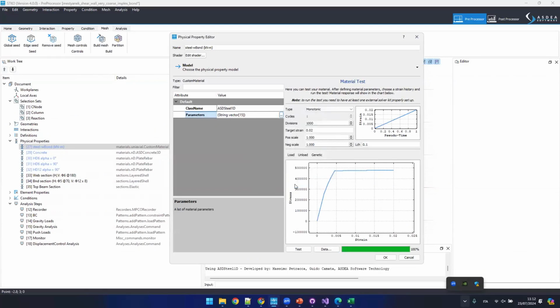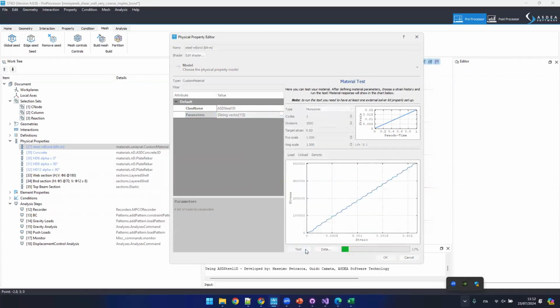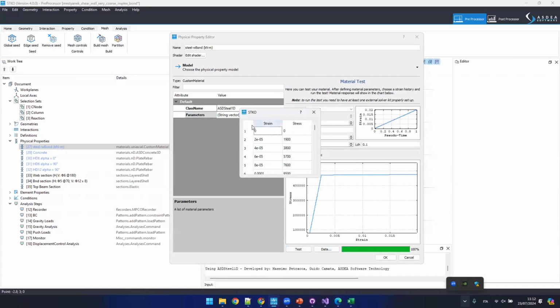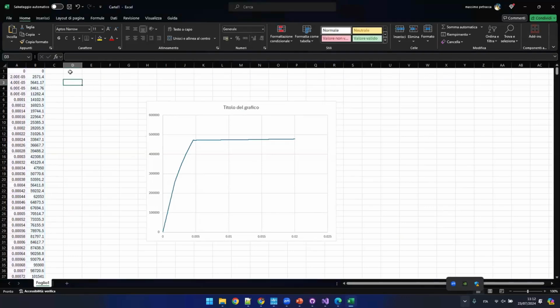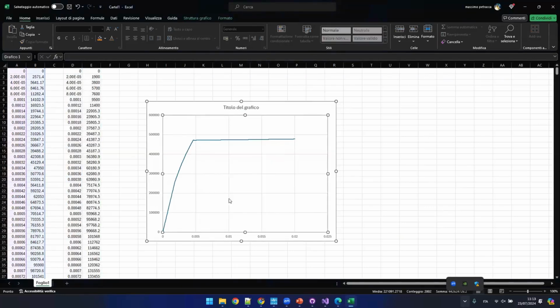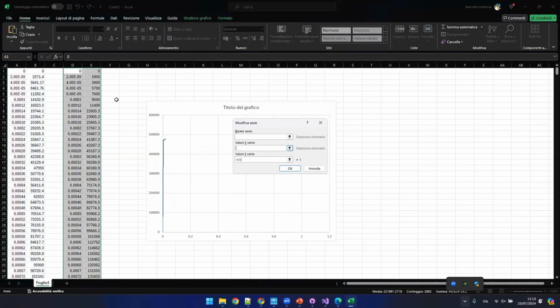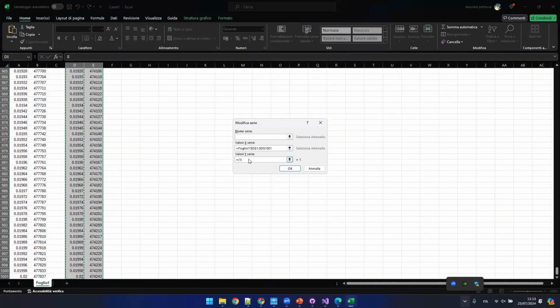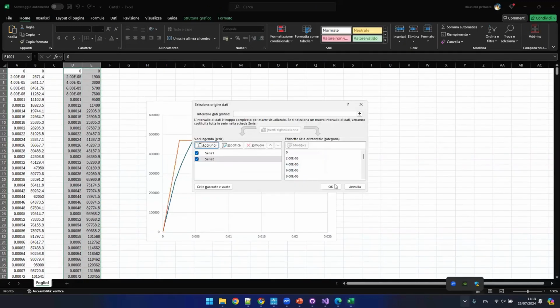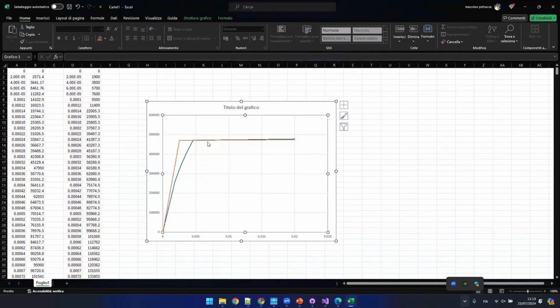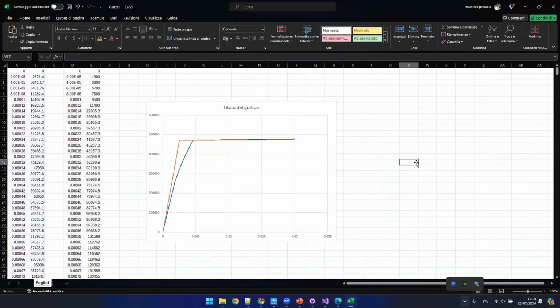So basically here I'm expecting to see just the behavior of steel, because now the bond will never be activated because I exaggerated its strength, okay? So for example, here, if I add new data, okay, you will see exactly the behavior of steel. So this is what the bond was doing at the beginning, okay?